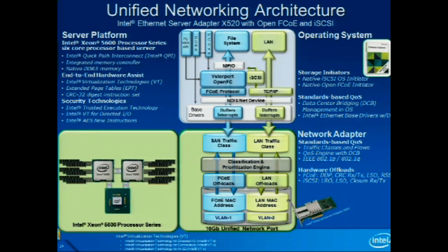So by having the protocol stack done by the native initiator, having the offloads and the data path done in the controller, and then being able to take advantage of offloads on the processor and chipset side and the performance gains, we take all 3 of those vectors and we can provide a high performance and highly reliable environment. You'll see some numbers coming out. We can drive full 10 gigs throughput of FCoE traffic on both 10 gig ports in the report that you'll see coming out.